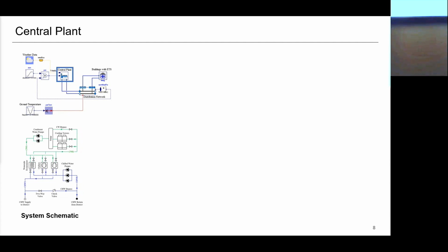Okay. So basically, we now have a model that looks like this, to model this heat extraction. It has radial heat conduction from the pipes, assuming some radial heat conduction into the soil. So that's something that we can model. We also have a model for undisturbed soil that you can use as the boundary condition here. But this one now assumes radial heat conduction, but the pipes are typically maybe a meter below ground, so the radial heat conduction is an approximation.